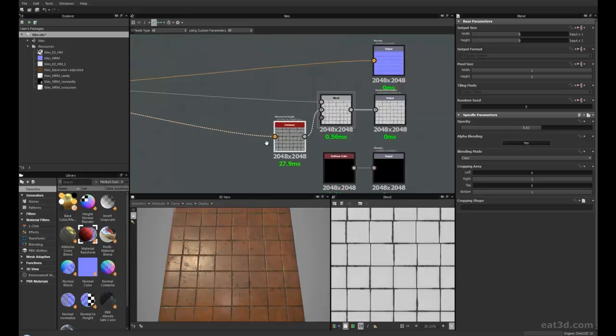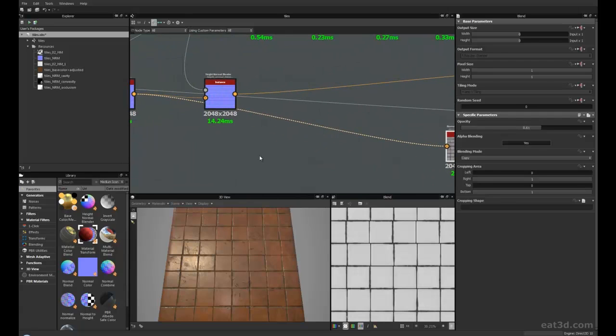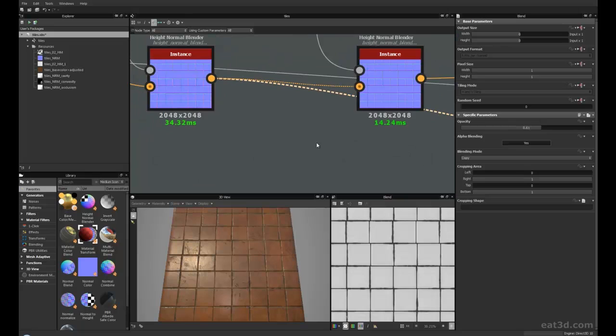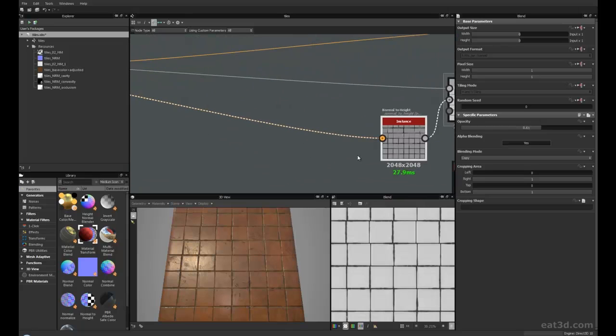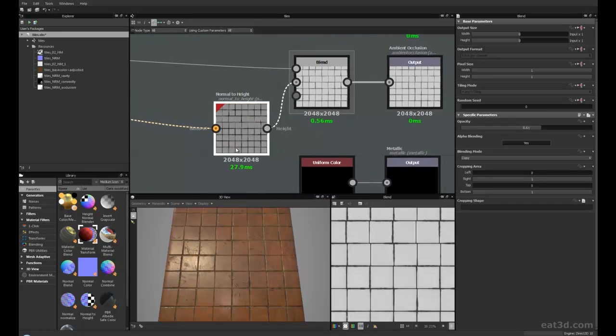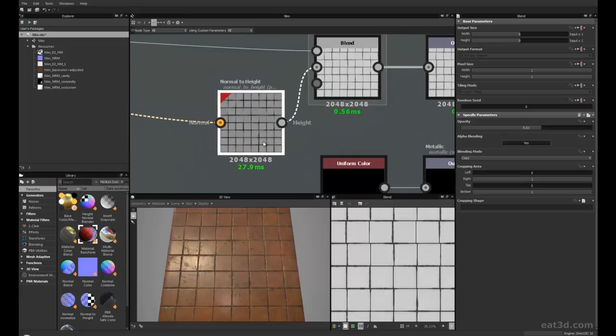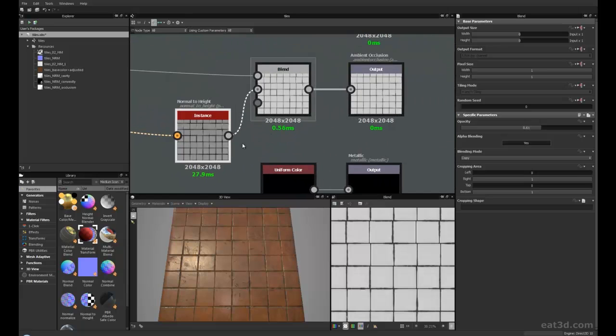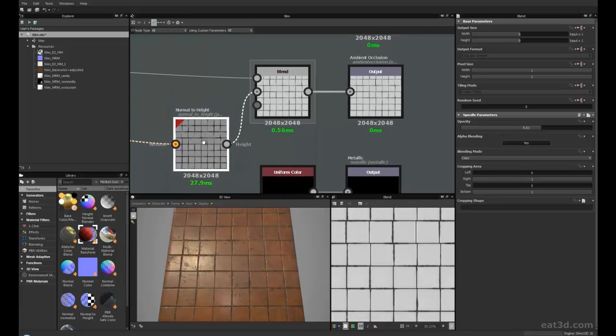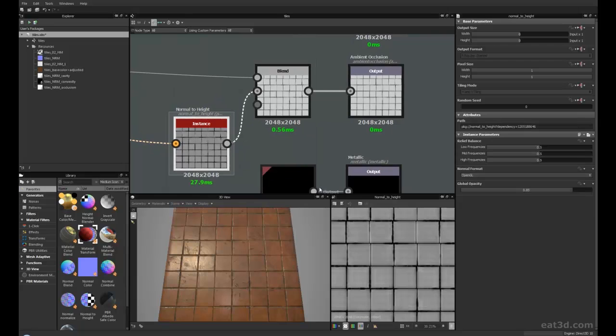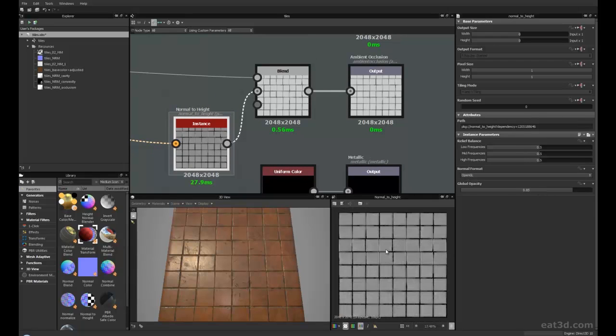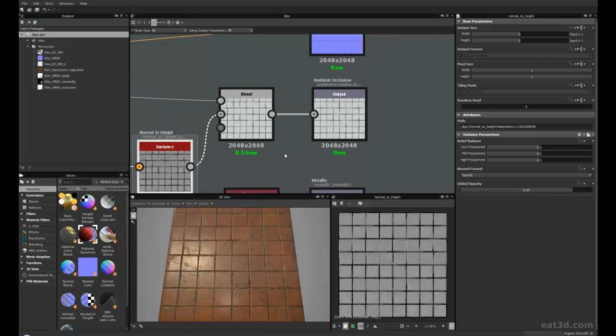What I'm doing this time is, I've got a bit of a normal because I've got lots of scratches and things. I'm going to start bringing a little ambient occlusion into that. The scratches are very small. It's probably better to do a cavity actually, and I may change that to a cavity, but at the moment I've got it as a height. So that's just created a height, OpenGL format, global opacity, and you can see this is what it looks like here. It's also quite nice because on top it's adding a little bit of darkness, but it's giving a few little lightish areas.